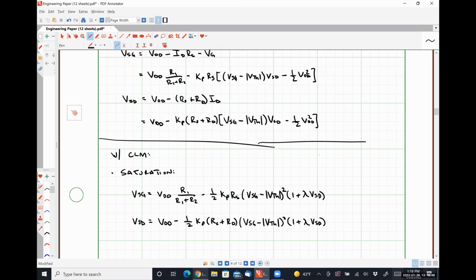And then just determining the DC operating point. That could be 3 separate questions, because I want to know VCE, VBE, and the collector current. Or for a MOSFET, I'm going to want to know VDS, VGS, and ID.